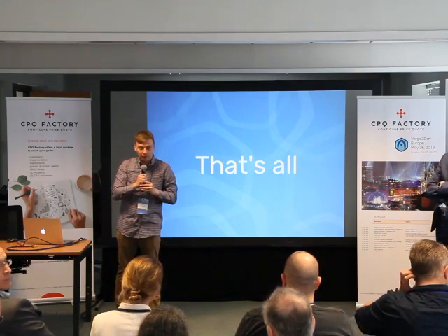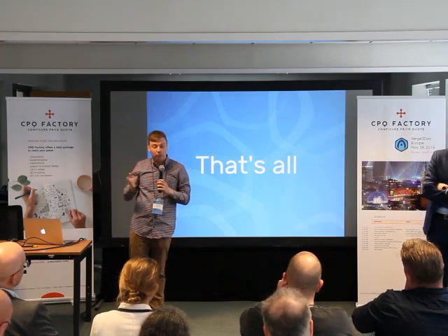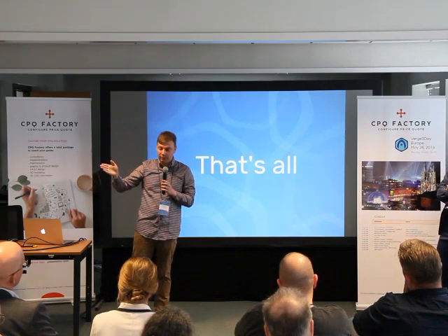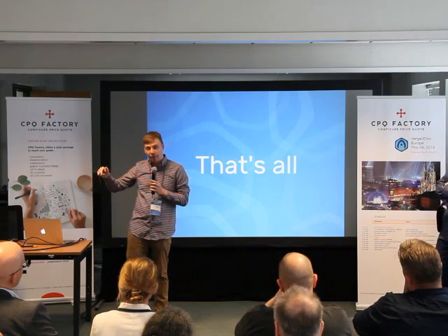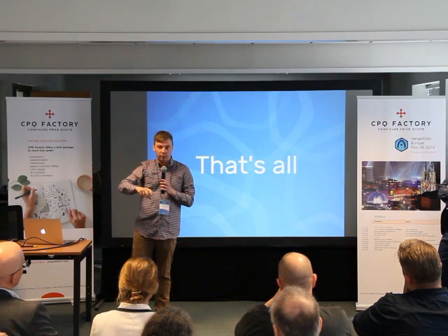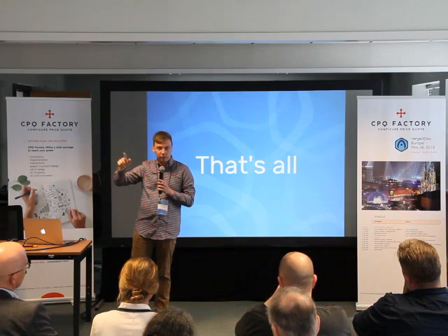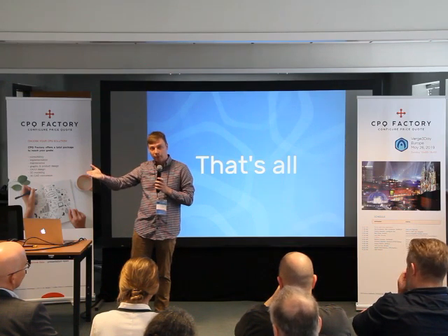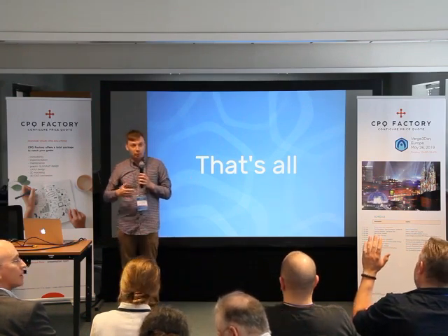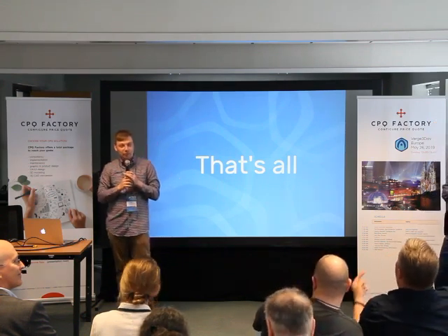You mean by colors? By channel? You can use the Blender Composer for this. There is a separate and combine RGBA node. You can put on the desk all these four black and white textures. Each of them connect to a separate layer, combine, render, and you will get the combined result. Or you can use GIMP, as I prefer. You can also find separate and combine in GIMP.